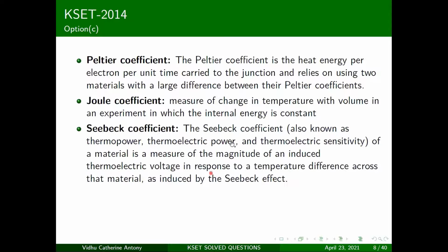So let's look at the next one. Seebeck coefficient. I want you to remember this term: thermoelectric power, thermoelectric sensitivity, or thermopower. One of the questions that we discussed in the last lecture, I think, involved talking about the Seebeck coefficient. And there, I think it was mentioned as the thermoelectric power. So that is basically the Seebeck coefficient. The Seebeck coefficient of a material is a measure of the magnitude of induced thermoelectric voltage in response to a temperature difference across that material. So now do you get it? You had a temperature difference which caused thermoelectric voltage.